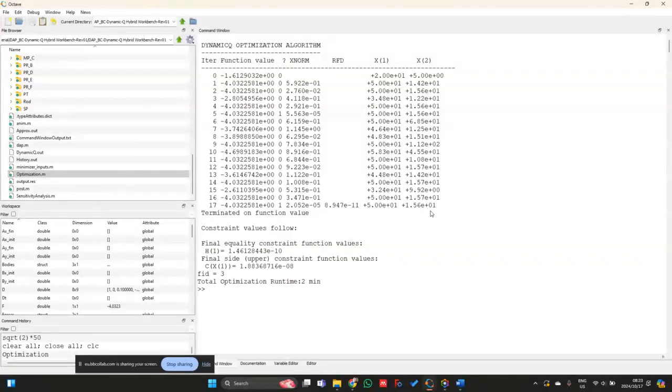And this is mostly due to the fact that I need a maximum velocity of 1.2 meters per second. So if I didn't specify the maximum velocity constraint, I would probably get away with a 0 value on the aerodynamic drag coefficient, since there's nothing really limiting the velocity.